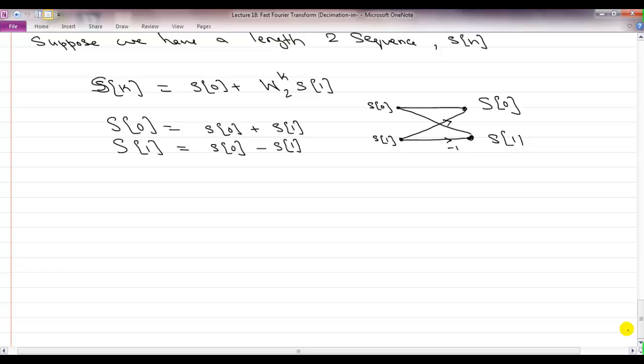What we want to now do is look at the cost of doing this recursive division to find out what is the final cost of computations in DFT, as opposed to using the direct formula. I just want to remind you at the first stage, stage 1, where we took our n length sequence and divided into two n by 2 sequences, and we said now compute the DFT of each n by 2, we ended up with this cost, n plus 2 times (n by 2) square.